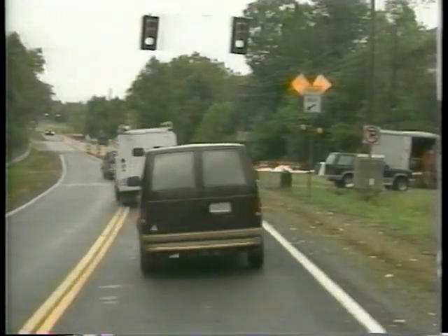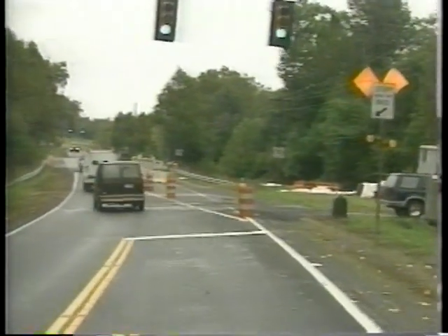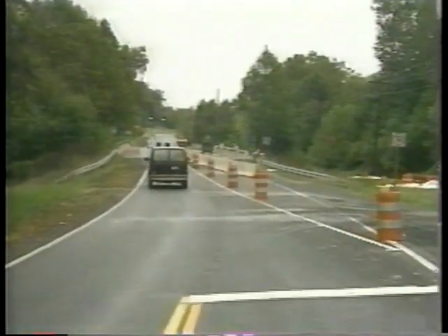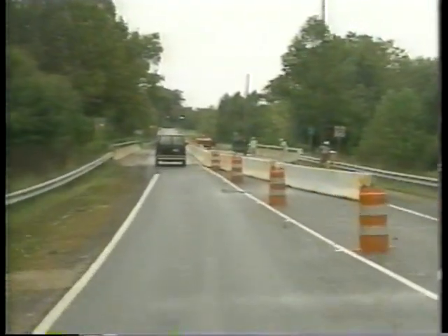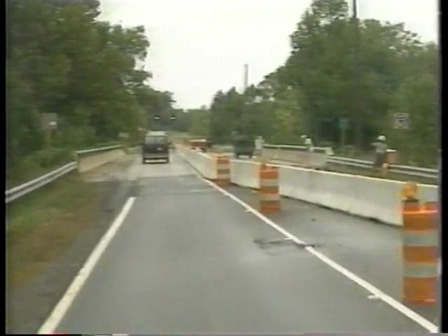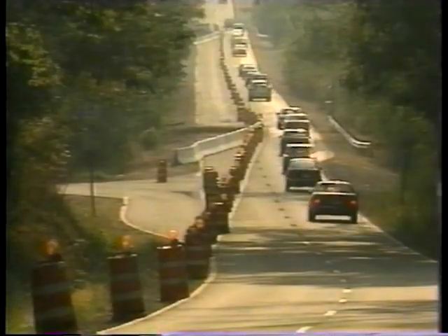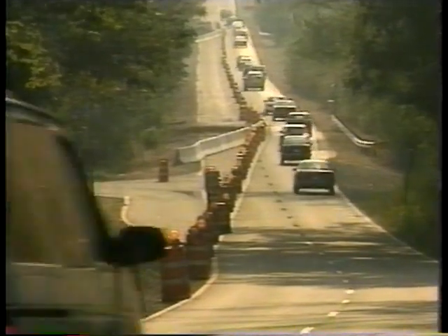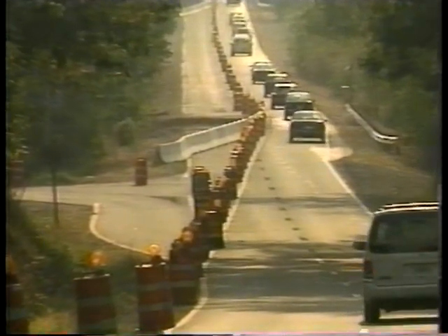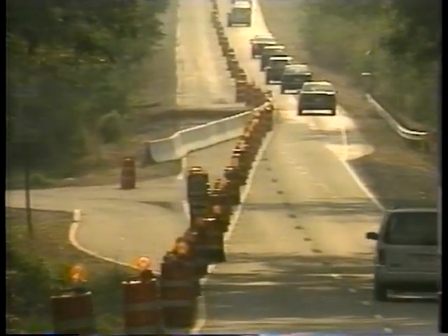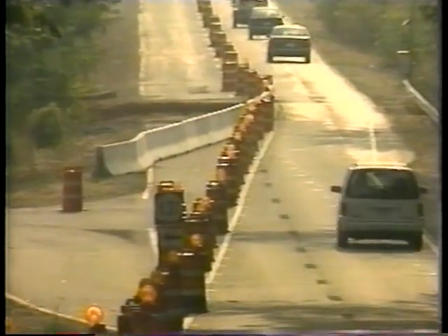The transition area moves traffic out of its normal path. This is especially necessary if work is being done in the traveled lane. The transition area channels drivers clearly to a new path. A taper is a series of channelizing devices and pavement markings placed at progressive offsets from the lane's edge to move traffic out of its normal path.